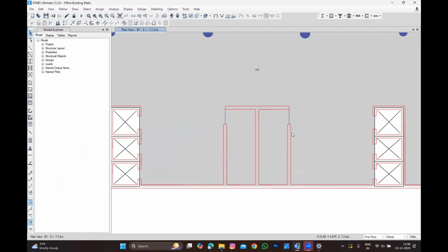Actually, on top of door opening, you do have spandrel everywhere. See, if you think it's a panoramic lift, actually, then it will not be there. Because in panoramic, full glass will be there. Only steel beam will be there. In that case, you cannot add it. Concrete will not be there in panoramic. And such a deep beam of 1.4, 1.5 in panoramic, no one will agree. Might be steel beam will be there.